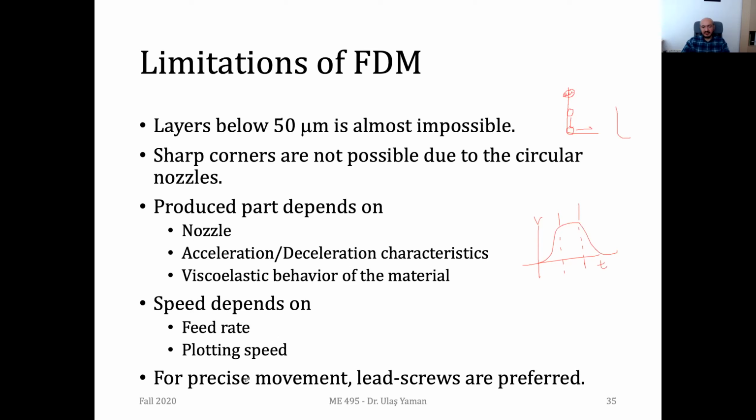And lastly, if you want to have more precise movements, then it's better you use lead screws instead of the belts and the stepper motors. Once you use servo motors and lead screws, then the accuracy will be much better.